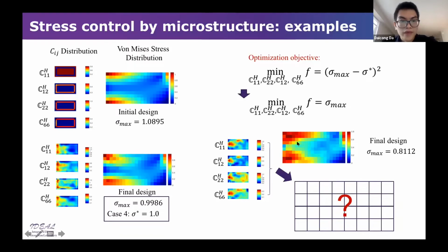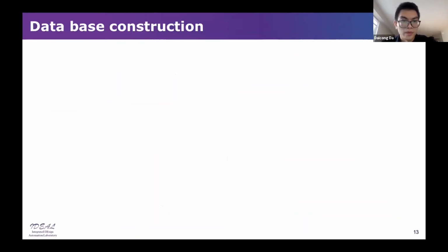And right now we have this stiffness distribution. If we want to validate the fracture resistance performance, we need to assemble the final structure based on each finite element location, and therefore we need a real dimension of each unit cell or each microstructure at each location of the finite element. So we have to find the unit cell and also assemble the structure.